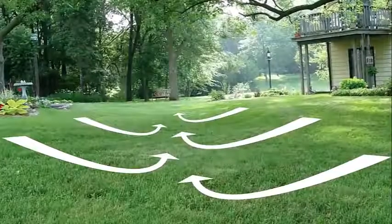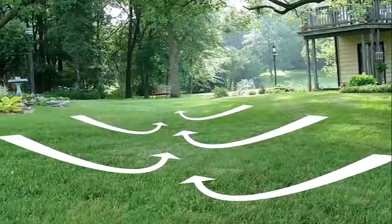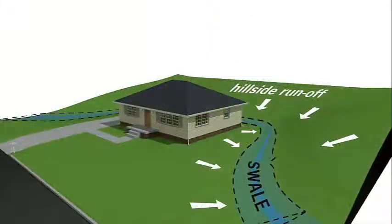All ground and landscaped areas along the perimeter of the foundation should slope away from the house and to an adequate distance in order to drain water away from the foundation. A swale provides a means to help divert hillside water runoff away from the home.